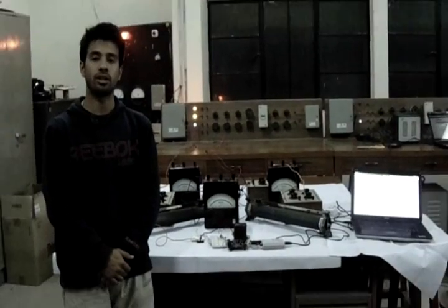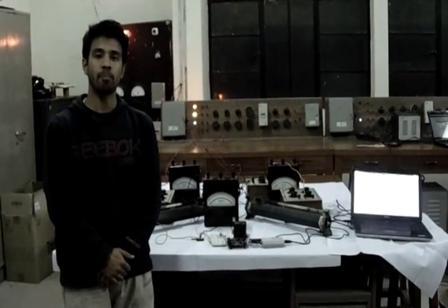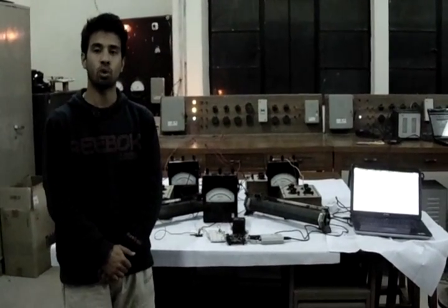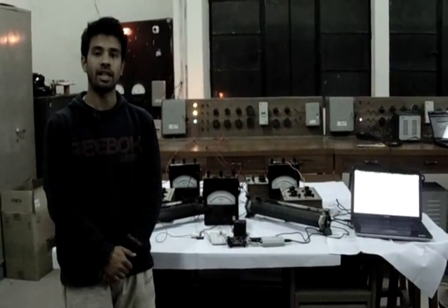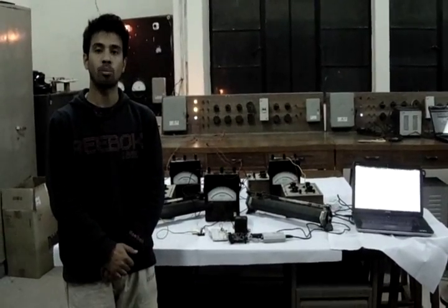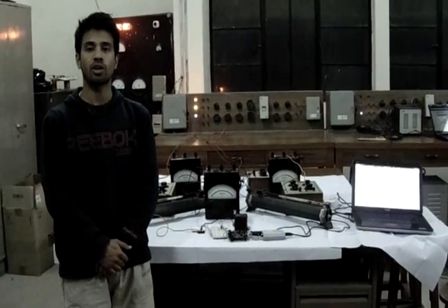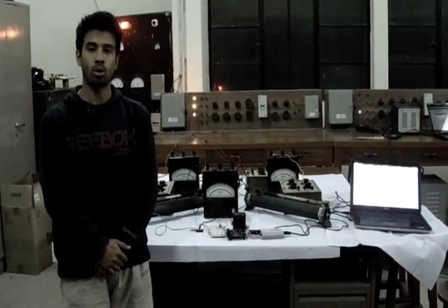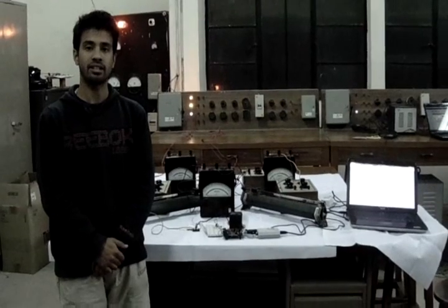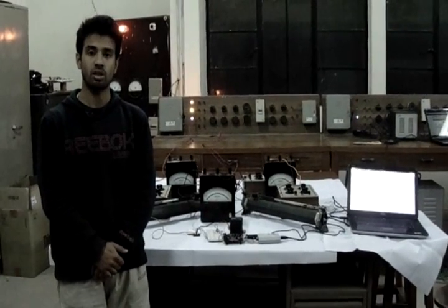Hence, we demonstrated how, by exploiting a simple characteristic of a 3-phase 4-wire system, the current at the point of common connection is almost negligible when the load is balanced. Thus, by the use of a current IC and experimenter board, we can measure that current and decide whether the load is balanced or not.